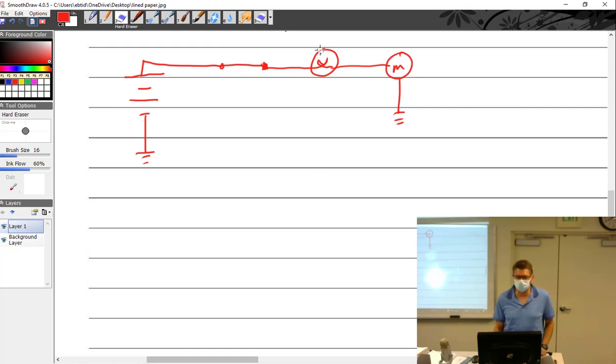So the only time when you can talk about running something in series is if I were in fact going to put a switch in series with the motor. Now there's a problem with doing that. And that is, this switch right here has to be then rated to handle all of that current. And if you think about how wires are run in a car or an aircraft, let's talk about something you're all familiar with, your car. You start your car, you put the key in and you crank it over, right?